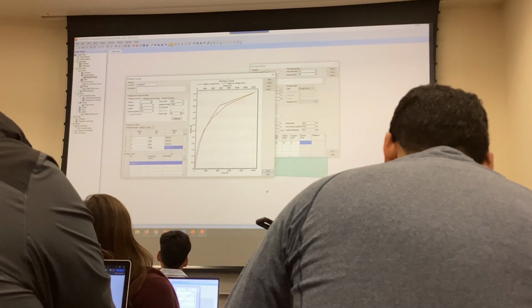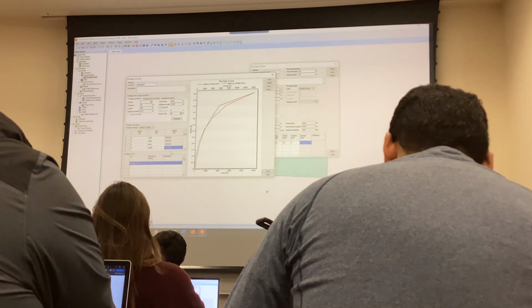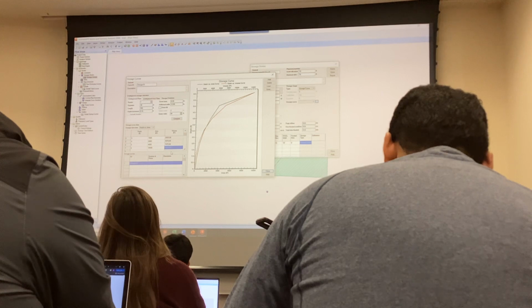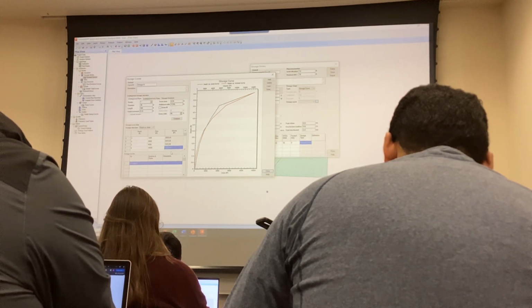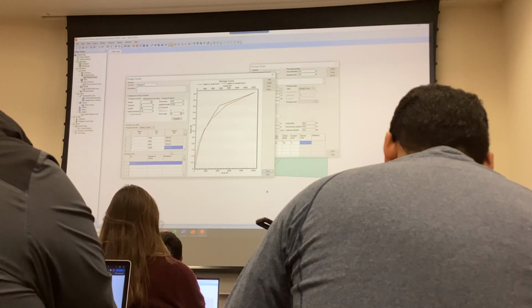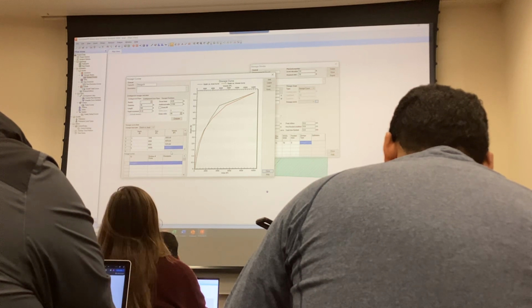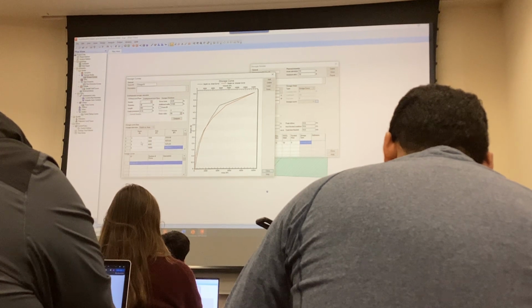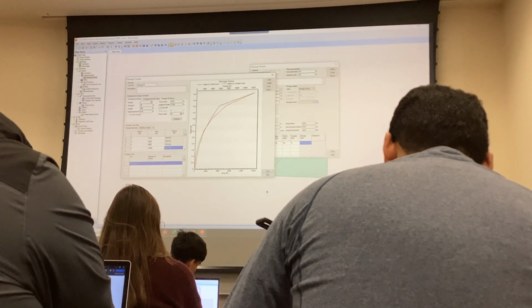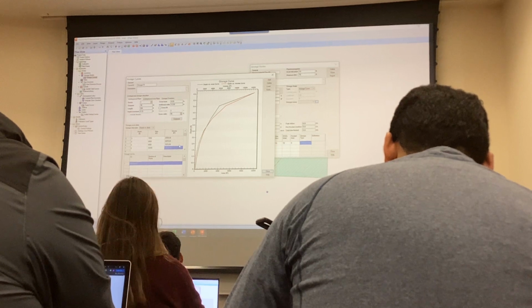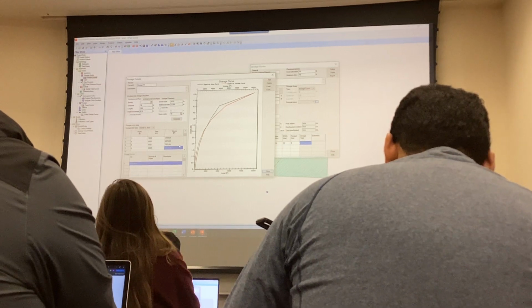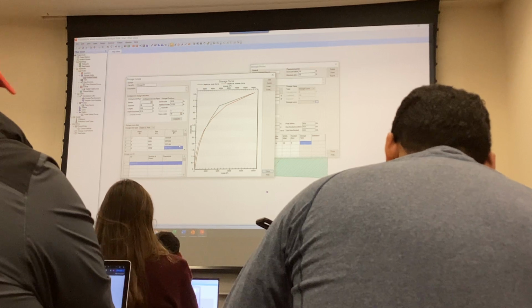Typically, the size of your detention basin gets larger as you go higher. If it gets smaller, that means you have a waste instead of a detention basin. So with that, it knows exactly the depth versus area. Remember how I taught you how to calculate the volume? It's doing the same thing. It's outputting the volume for you between each consecutive layer.